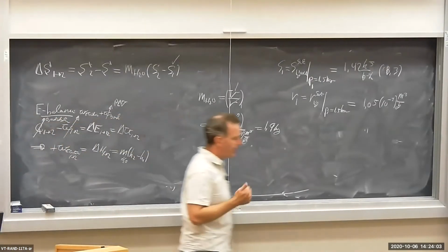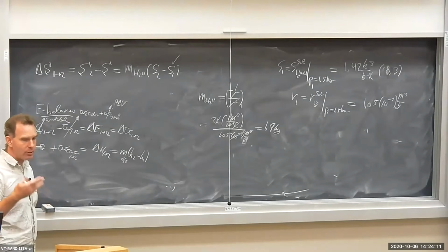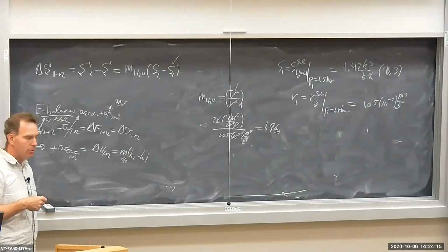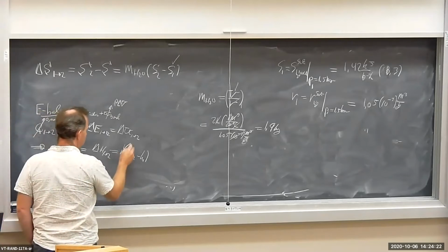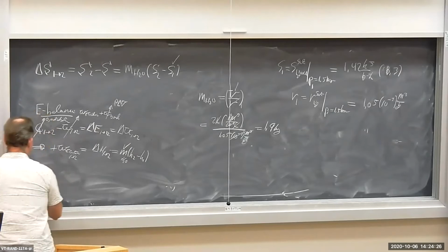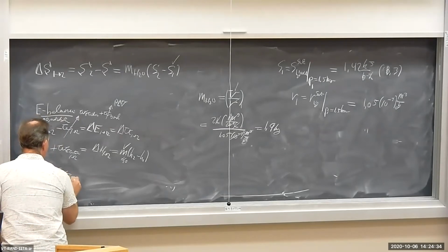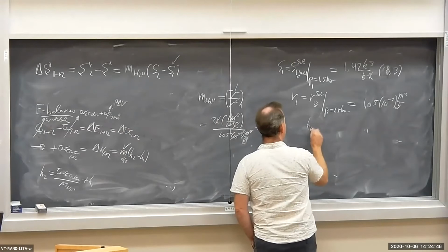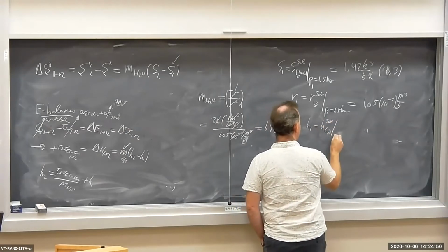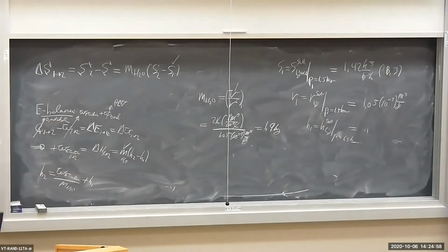All right, so to get S2, I need either a specific internal energy or enthalpy to get a quality at state 2, so I can calculate the specific entropy, okay? To do that, I need to solve for H2. I have m times H2, so let's solve for H2. Divide both sides by m_H2O, and I get W_electric divided by m_H2O plus H1. I don't know what H1 is. H1, I'll look it up in a table. H1 is H of the saturated liquid evaluated at a pressure of 1.5 bar. So I'll look that up in a table.